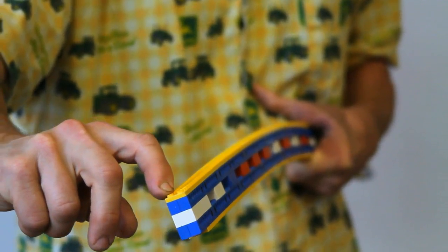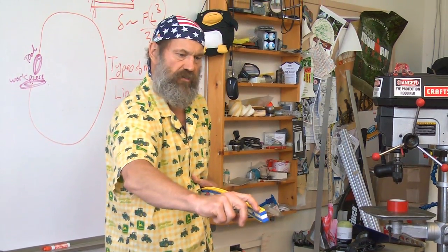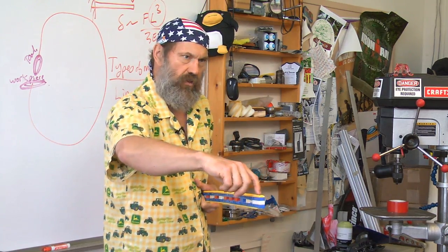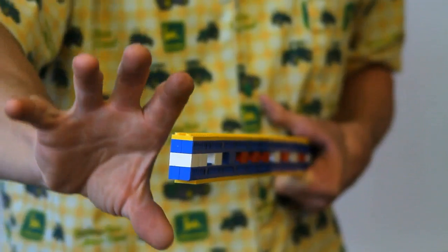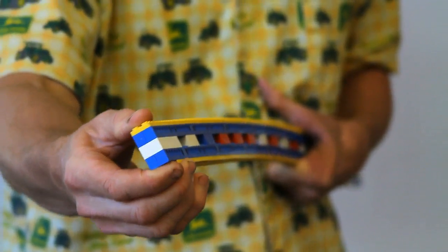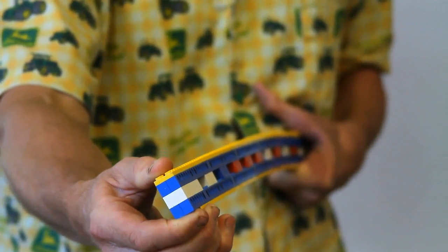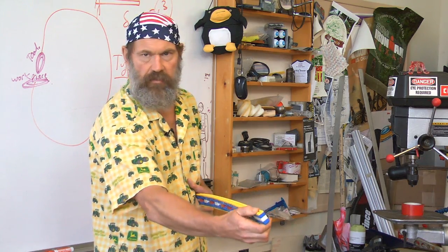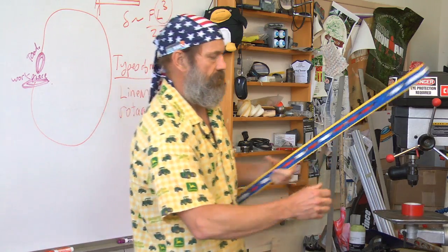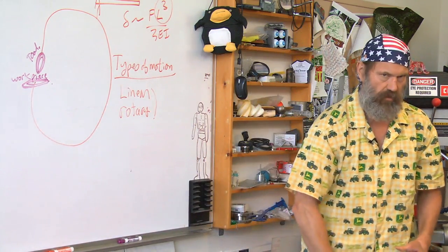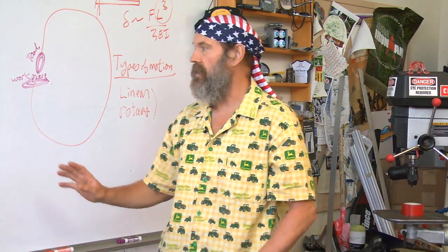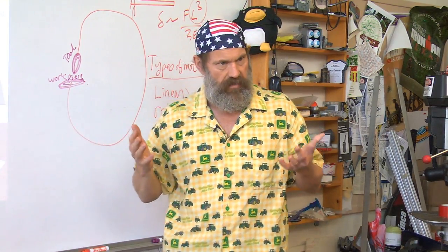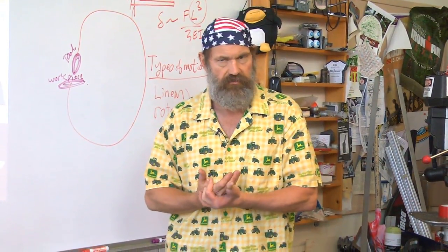See how it twists? A very common failure mode in a structure is if you take a beam and it's not loaded through what's called the shear center of the beam, you'll get a torsion which can then cause it to buckle and fail. So you have to be very, very careful how you actually load beams to ensure that they don't have one of these torsional instabilities in bending. So make sure you really go back and learn your mechanics of materials very well. As a design person in a design class, understanding the mechanics of materials is absolutely critical to building the structure.